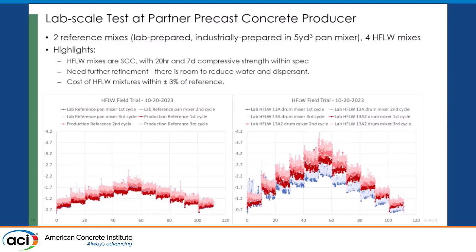Here are the references. There are 2 mixes here, the reference from the 5-yard mixer, and the reference made in the lab. And there are 3 different shades of color here, 3 shear cycles we do, waiting 5 minutes in between each. So we see there is some buildup of the properties here. The best mix that we had was this blue one here, which is not too different. They are the same scale. Sorry, this is torque, and this is time, okay? So the blue one was our best high filler, low water result. We still have room to improve, and we're going to work on that to come to the level of energy that the reference mix requires.